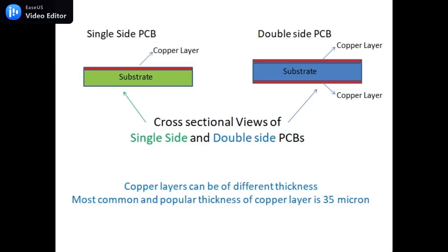Okay, now what is this PCB? We have seen the PCB board in the last slide. But what is this PCB board made up of? What is this board actually? This PCB, or PC board, is actually a substrate. It is just a non-conductive material and there is a thin layer of copper deposited on this substrate. The thickness of the copper layer is 35 micron.